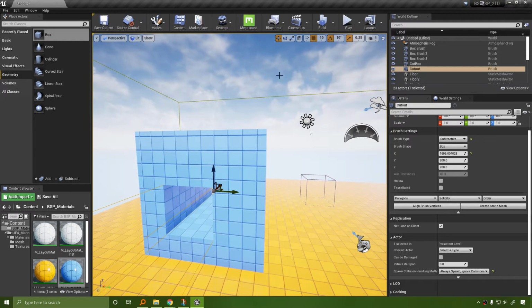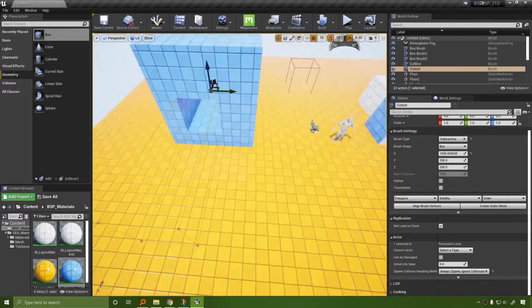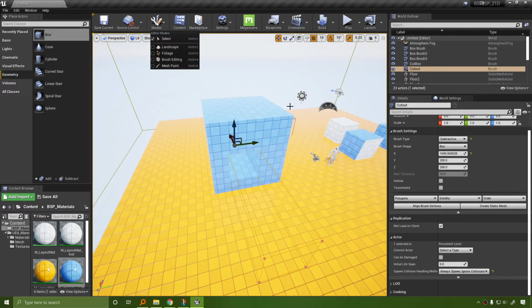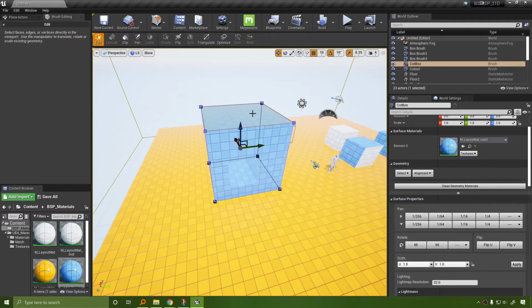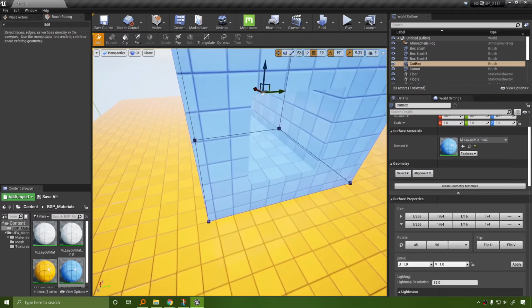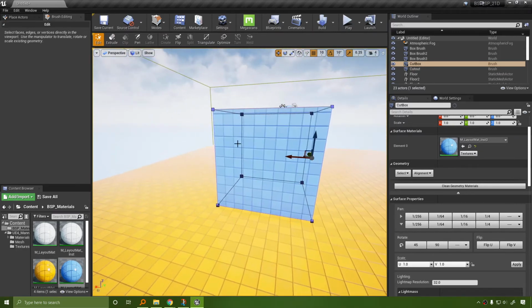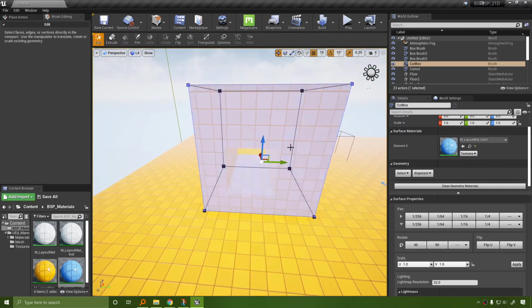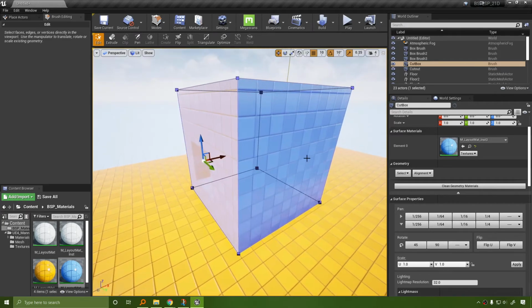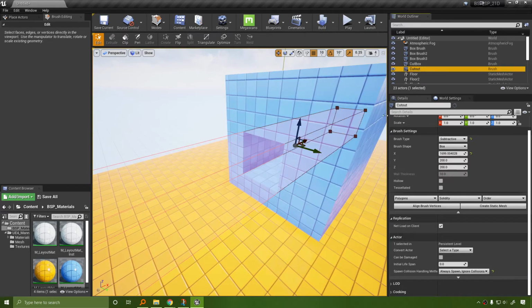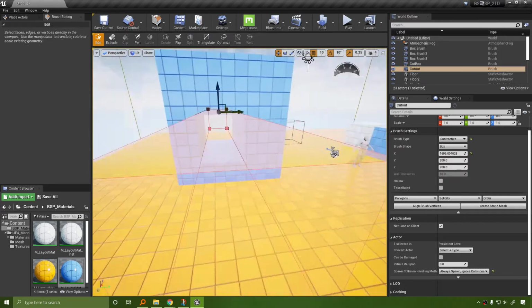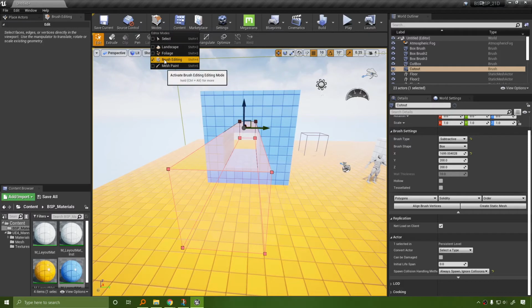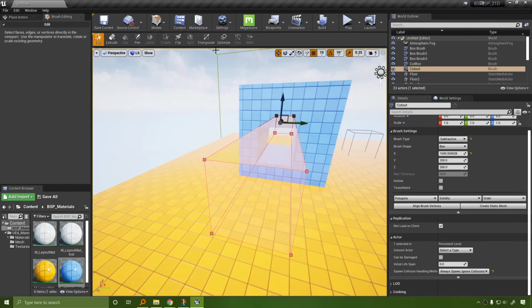Once you start modifying or scaling your shapes outside of the default brush settings is where your brush editing can make things a little bit more difficult. Because now, as you can see, I can edit this brush, but it doesn't acknowledge that intrusion right there. This cutout, same thing. If I select this cutout, I can, under the modes panel, go into the brush editing. What it does is it edits your brushes. You can edit your brushes using the brush editing tool.